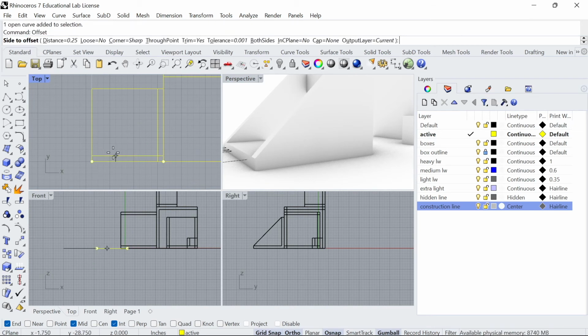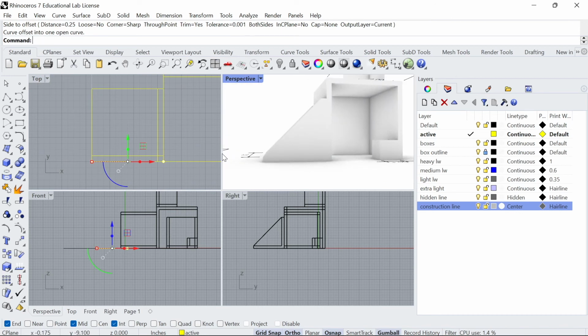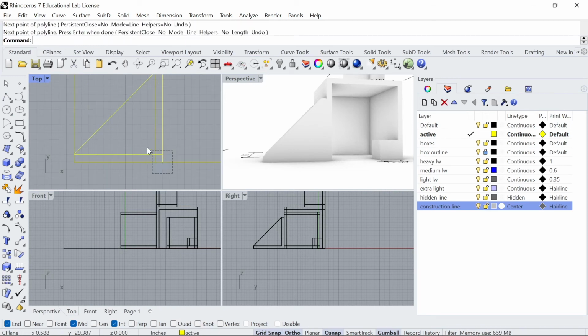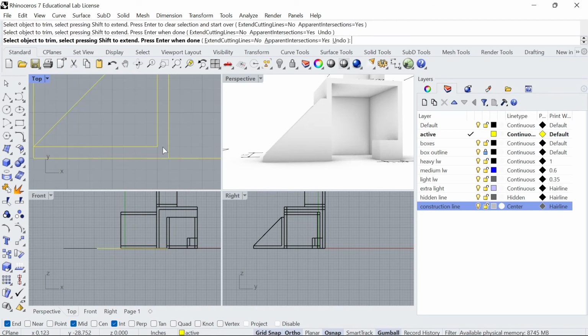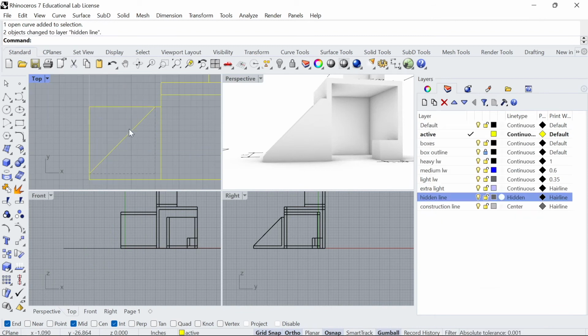And this is going to be one of our hidden lines because you can't actually see it when you're looking at it like this, in a side view. So it will be a hidden line, but it's here to help me determine where that diagonal goes. Okay, so draw that in. Okay, and then I'll go ahead and trim this overlap because that doesn't actually exist, and I'll change these to hidden lines. And then I'll go ahead and trim what I don't need, which is these two edges.